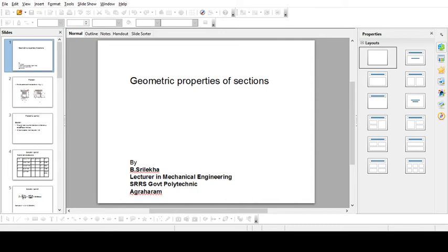Okay, so this is also you have to remove the material. Sorry, here we are not going to remove the material because here no hollow space is there, the entire region you have to find. So the area is pi r square by 2, which is equal to 353.25 mm square.